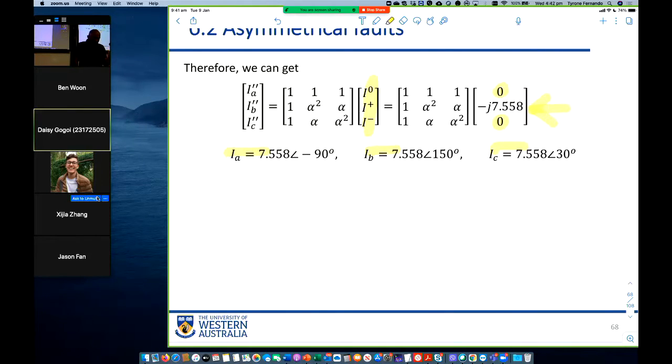When you have drawn those three separate circuits to do the fault calculations, at the bus terminal where the fault occurs, you find the Thevenin impedances for all three circuits. That is easy. If there are some source voltages in the circuits, you turn them to 0 and just find the Thevenin impedances.